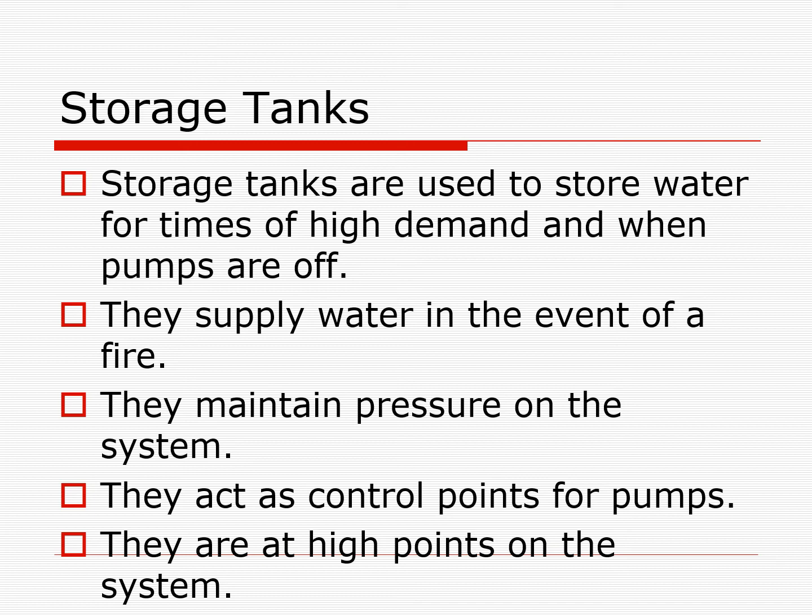The water going up and down in the tanks is also done so that water does not become stagnant. So there's always water flowing through that throughout the day. They supply water in the event of fire. They maintain pressure on the system, and they are at the high points of the system.